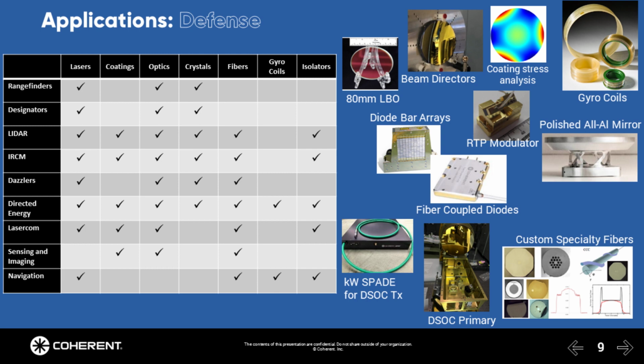And so you need relatively large optics with very, very high reflectivity coatings. And this gets back to what I was talking about earlier, making sure your coatings aren't stressing your optics and deforming them. You can see here an example of an analysis on a thick coated optic, where because of the light weighting on the backside of it, when you put this coating on it, it deforms the optic, and therefore you need to pre-compensate for that when you polish your mirror before coating.